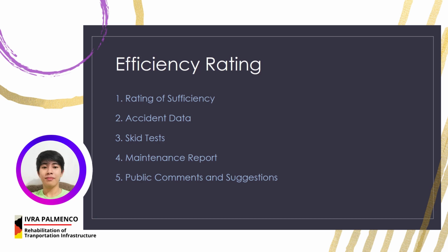The first being the rating of sufficiency. The rating of sufficiency is a tool that is used to help determine whether something that is structurally deficient or functionally obsolete should be repaired or just replaced. It considers a number of factors such as cost, reliability, and efficiency, and is ultimately the basis in deciding which projects are either continued or terminated.